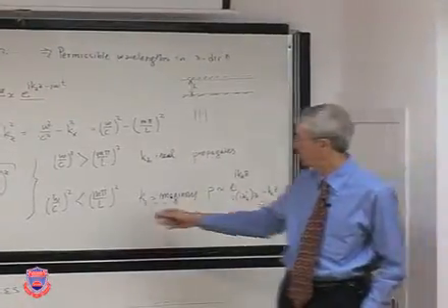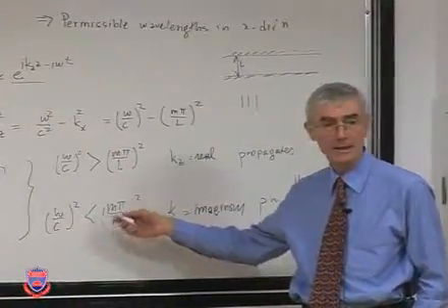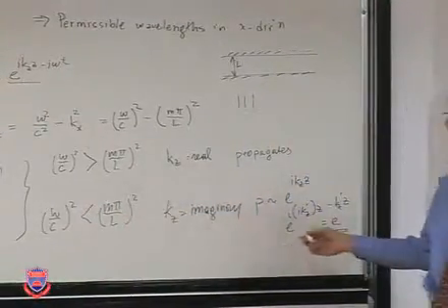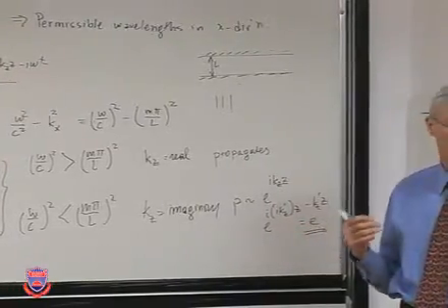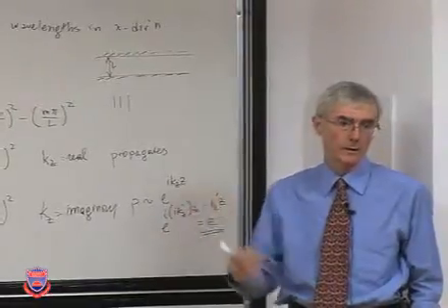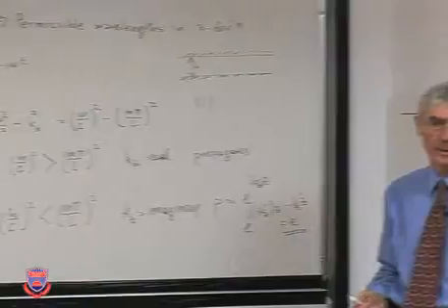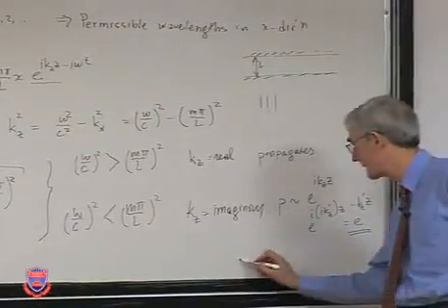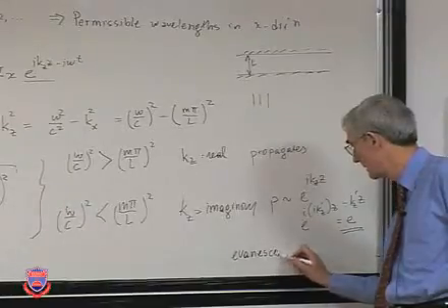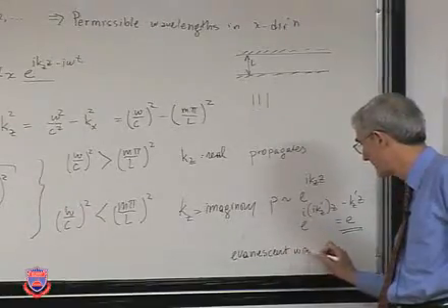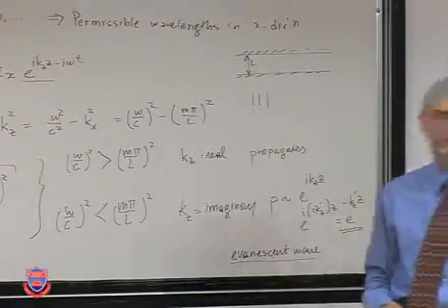Okay? So if it is at a frequency that's less than a corresponding mode, that will not travel down to the far field in the waveguide. And it becomes what is called an evanescent wave. It dies out very soon.